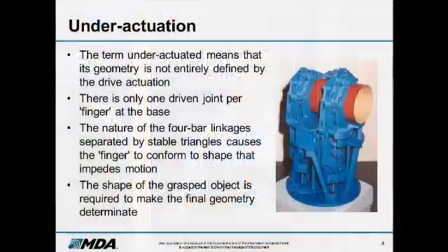So what is under-actuation? It's the title of the presentation. Under-actuation means a number of things. One, the self-adaptive portion is that the manipulator fingers adapt to whatever surface they're grasping. And it's only driven by 1 degree of freedom per finger. In fact, this hand has 3 fingers and 9 degrees of freedom, and it only has 2 actuators, one to reorient the fingers and one actuator to actually pull them all down at the same time. So you could even reduce it further.